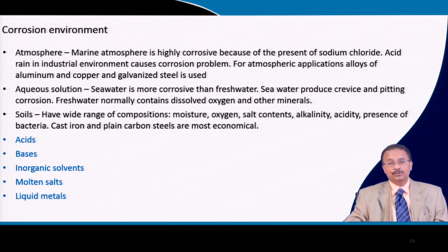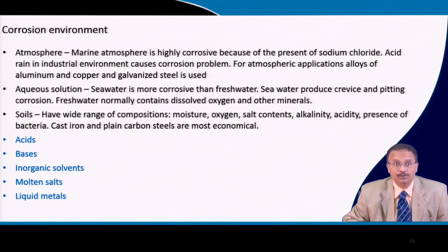Aqueous solution also could be corrosive. Seawater is more corrosive than fresh water. Seawater produces crevice corrosion and also pitting corrosion, and fresh water normally contains dissolved oxygen along with other minerals, which, because of their reduction nature, can also corrode the metal.